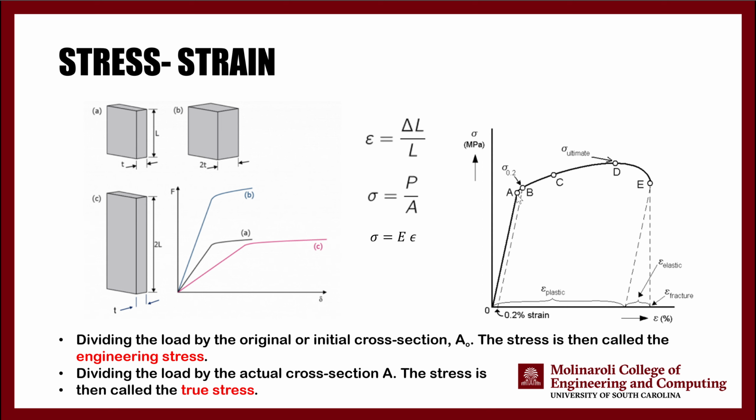You are going to apply a load, and because of that load there will be elongation, and you will see a very small linear region. The linear region will be followed by a plastic region, and then eventually you are going to see a rupture.